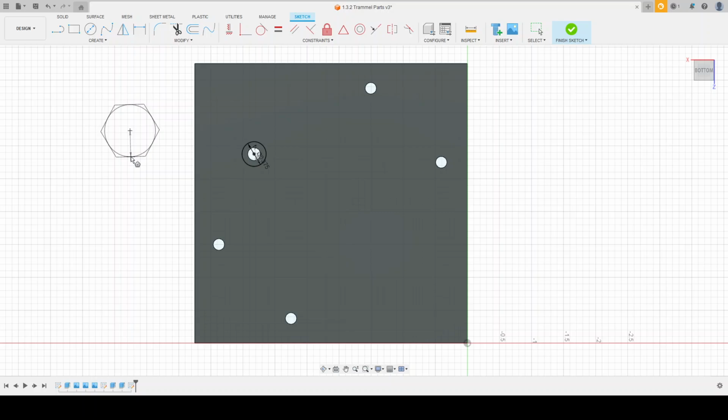Either case would work. It's just dependent on which one you have done. I think this hexagon will be easier to measure across, since you have wide flat areas to measure against, versus if you did the inscribed and were measuring corner to corner, it can be a bit more difficult to get your calipers all the way into that corner. So I would recommend doing the circumscribed, but we can do inscribed as well.